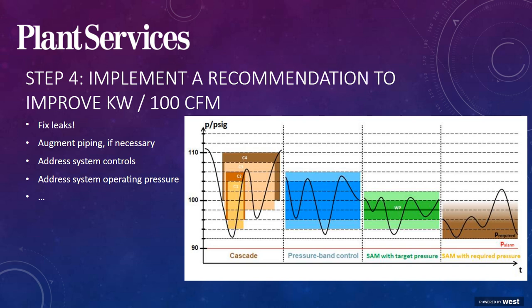And so now you can see where that band is even tighter still and lowering that overall operating pressure. So now looking to the far right, you can see where we actually set a floor, and then that pressure is adapted to various demands. So in short, adding a master controller can reduce your overall system pressure while providing the huge benefit of ensuring each compressor is running as efficiently as possible, as well as the overall system.